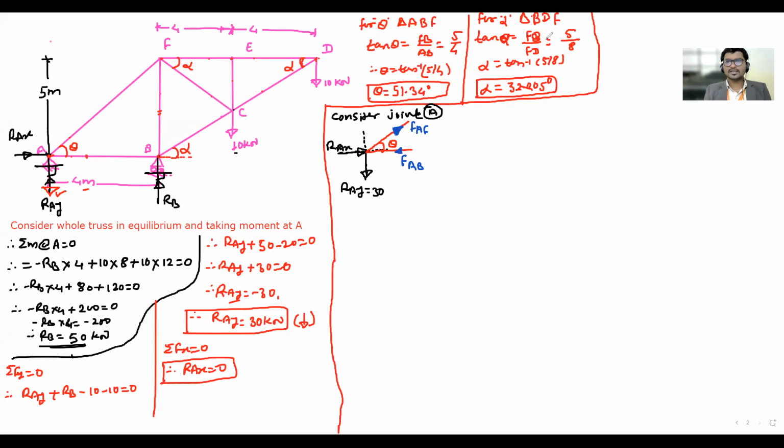Okay, is everyone done up to here? Yes, sir. Those are completed. Go for the conditions of equilibrium. Which condition do you want to go for first? Summation of y. Summation Fy equals 0. Therefore RAY plus or minus? Minus, since RAY is coming down. What about the component of AF, which is going up as per the assumed direction? Positive. AF sine theta equals 0.